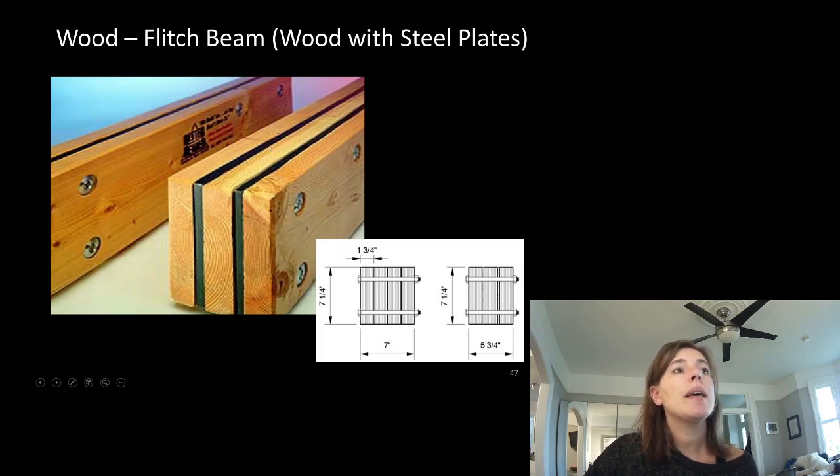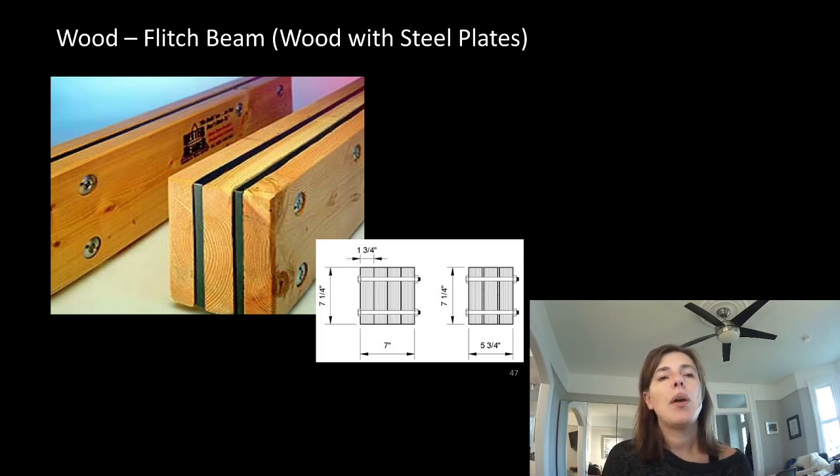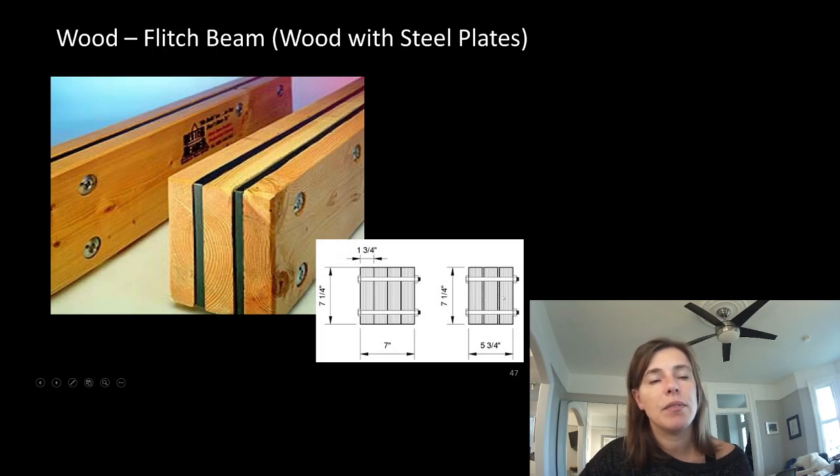So if we combined the beam and the steel, each of these is doing part of the job of carrying some of the load. And in 2 weeks, we're going to talk about load sharing versus composite materials. We are able to get rid of 1 whole ply of wood and replace it with these 2 thin plies of steel. Why wouldn't we just make more plies out of steel? Because it's more expensive. And we're doing a wood building here, so we're trying to go with the cheapest option available.